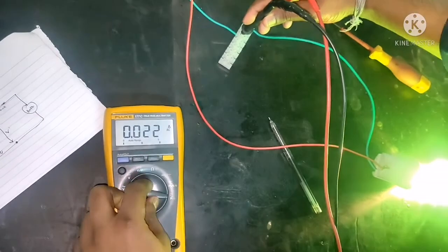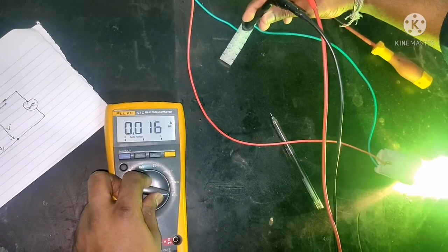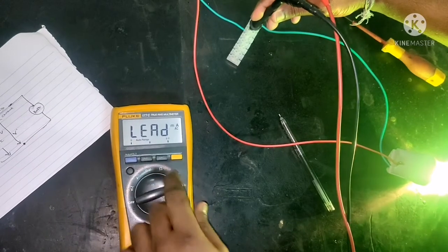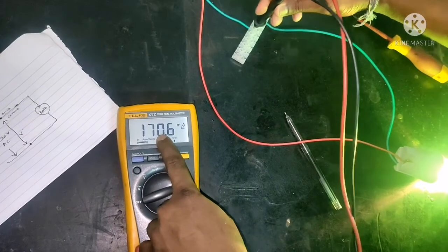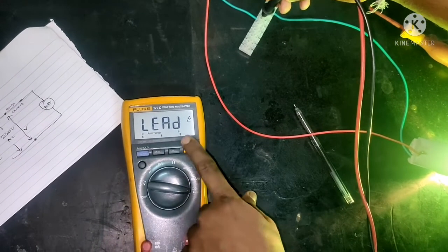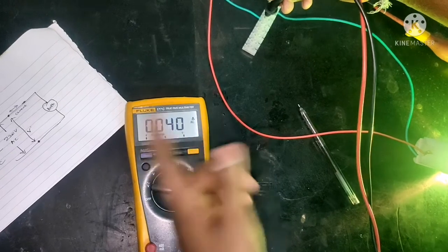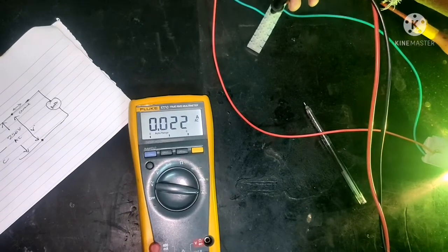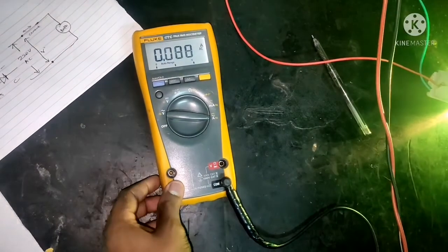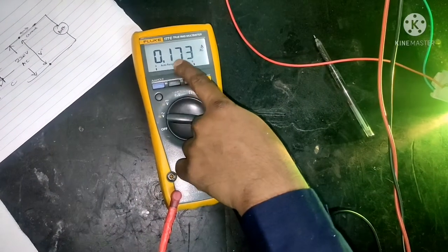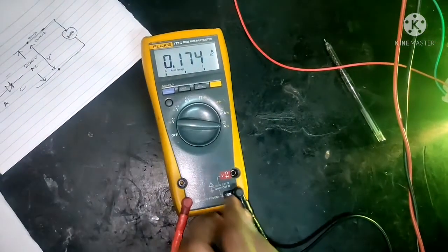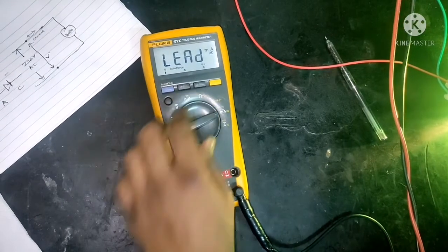So now you can see the value in amps. You can see the amps value is showing very little. The reason is that earlier the milliamps value was 170, so the amps should be 0.17, but why is it not coming? The reason is we need to change the plug from the milliamps terminal and put it back to the amps terminal. So now you can see the value is 0.17. So always ensure you are plugging the lead in the correct terminal, so that you will get the correct value.